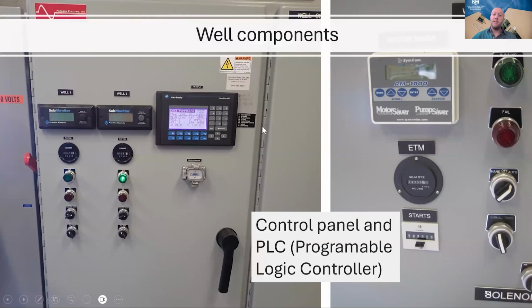And then, of course, there needs to be some sort of controls for your well pump. That could be as simple as just having a timer for your well to turn on and off for a certain number of hours a day. It could be connected to a float in your tank, so that when your tank gets below a certain level, it turns on that pump and fills it up. Or it could be something all the way up to PLCs, programmable logic controllers, connected to a SCADA system. It could really go from very simple to more advanced.